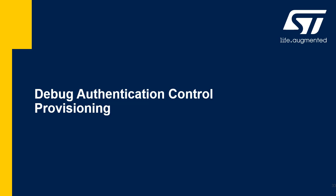Debug authentication is natively supported by STM32H5 platform. It means that the data used by Security-Debug-Authentication must be provisioned at a defined location in secure key storage area. This will be described in the next slides.